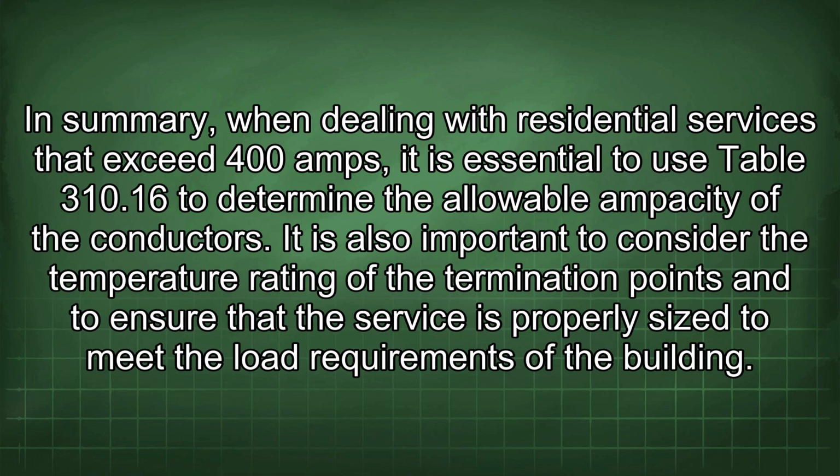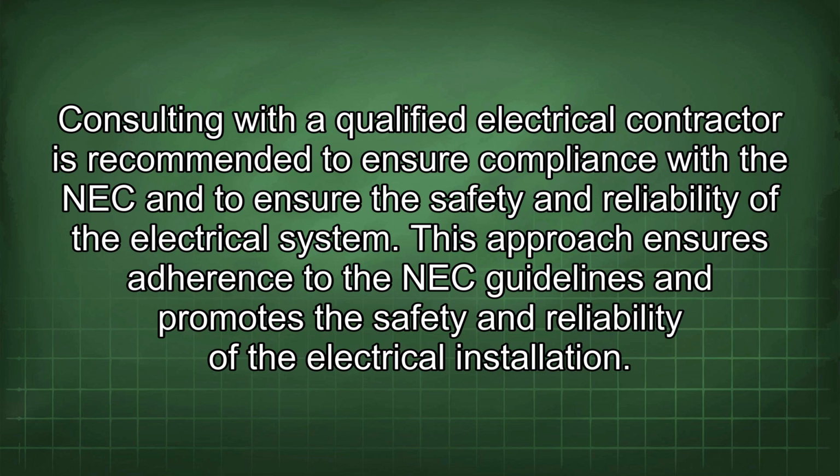In summary, when dealing with residential services that exceed 400 amps, it is essential to use Table 310.16 to determine the allowable ampacity of the conductors. It is also important to consider the temperature rating of the termination points and to ensure that the service is properly sized to meet the load requirements of the building. Consulting with a qualified electrical contractor is recommended to ensure compliance with the NEC and to ensure the safety and reliability of the electrical system. This approach ensures adherence to the NEC guidelines and promotes the safety and reliability of the electrical installation.